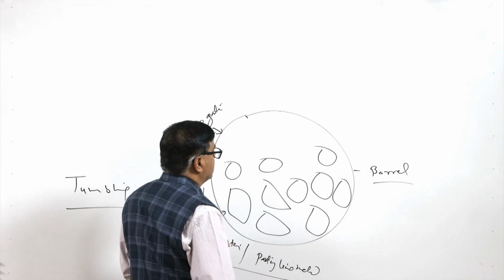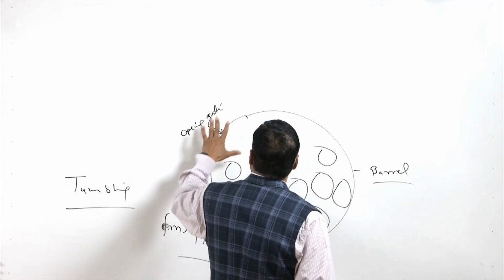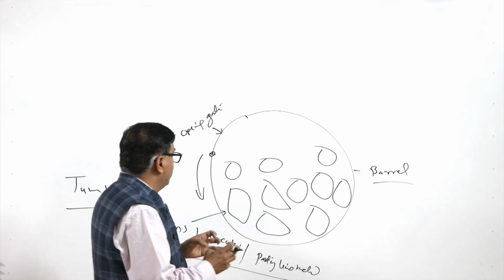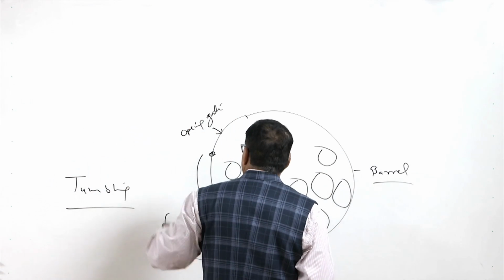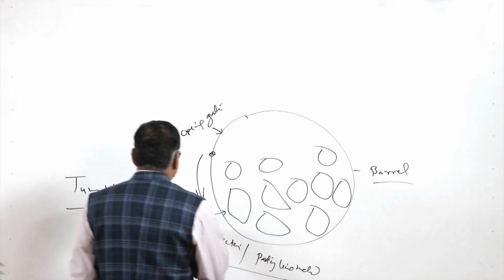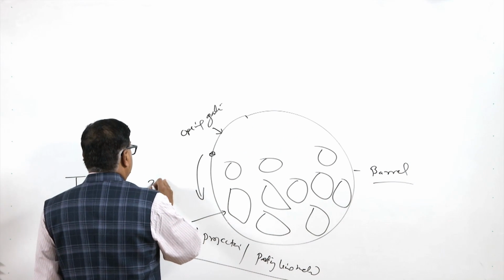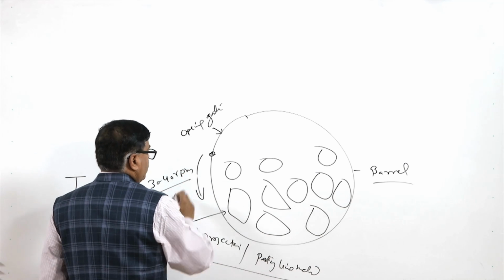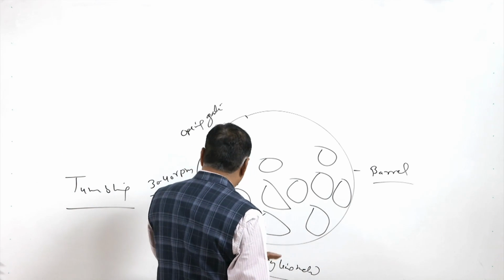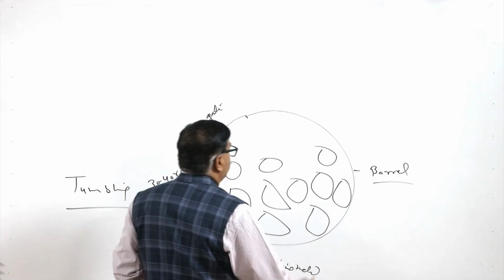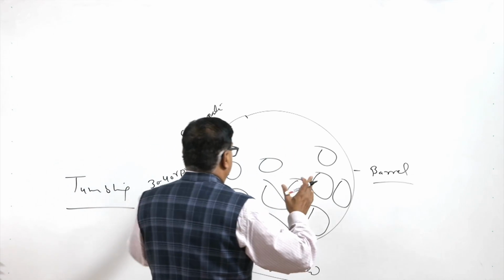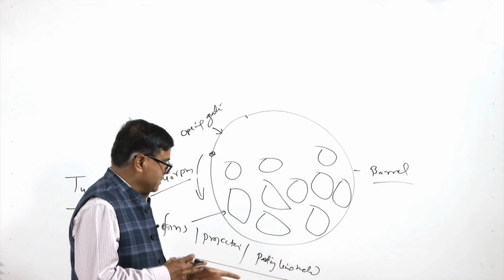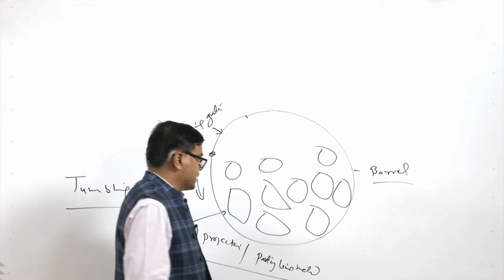Even the fused sand is easily cleaned when the castings' surfaces rub with each other, and the barrel is rotated at quite low speed, like 30 to 40 rpm. So, this is the kind of speed which is used. Continuous rotation of the barrel leads to the rubbing of the surfaces of the castings with each other and thereby removes all these things.